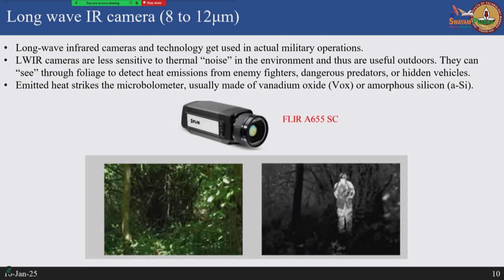And long wave IR cameras are also used for scientific purposes, and in military applications, for example. They are less sensitive to thermal noise in the environment, so they can also be used outdoors, unlike the mid wave IR cameras. These sensors are what are called microbolometers, and they are made of vanadium oxide or amorphous silicon. The A655SC that we have is a scientific camera